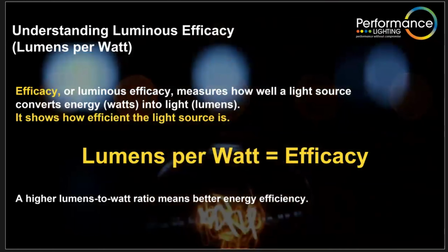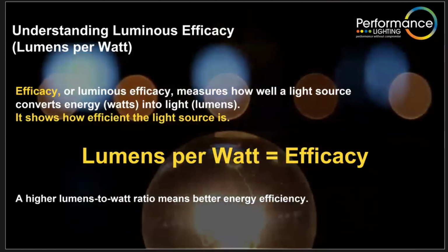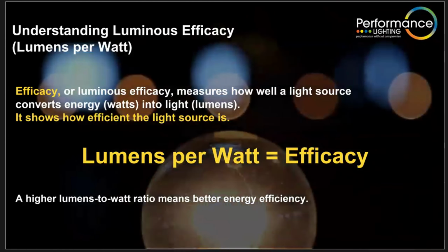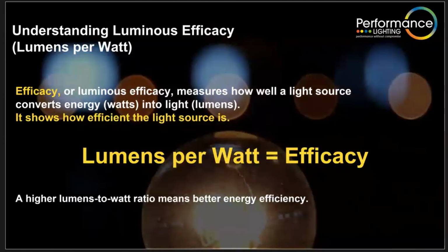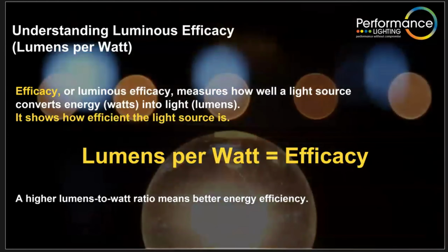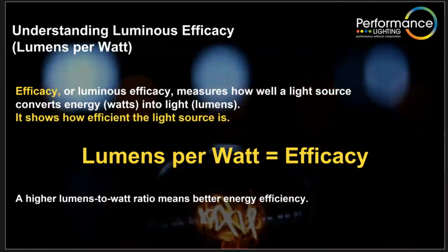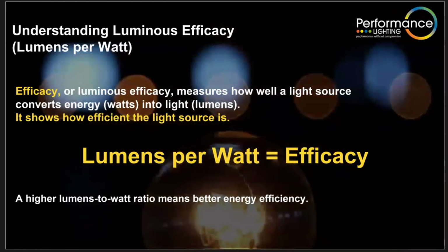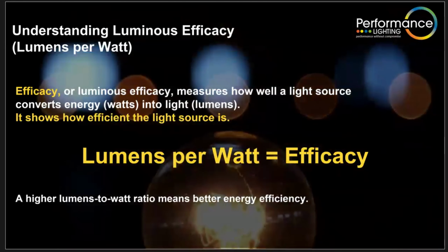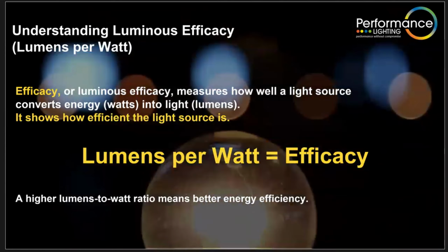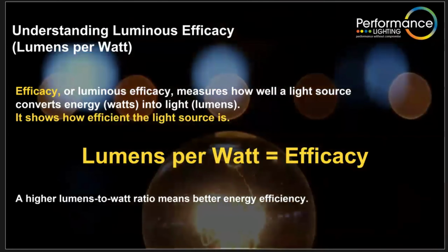Talking again about the older technology, a 5-foot fluorescent tube, T8, was always 58 watts, circa 5,000 lumens. Again, there is lamp degradation, which I briefly touched on, but straight out of the box, 58 watts, 5,000 lumens. With control gear losses, it probably cost you in energy 62, 63 watts to actually power that 5-foot 58 watt tube.